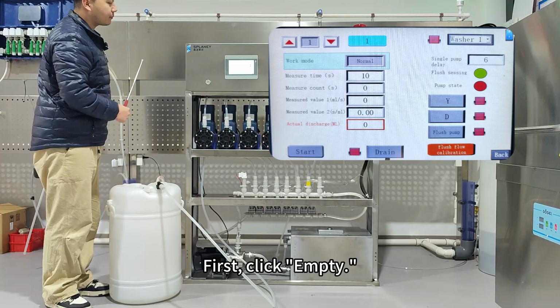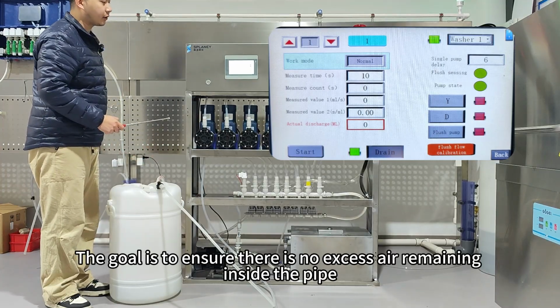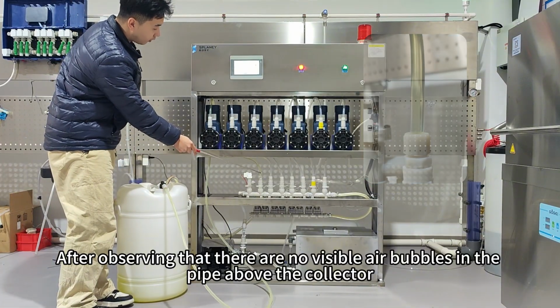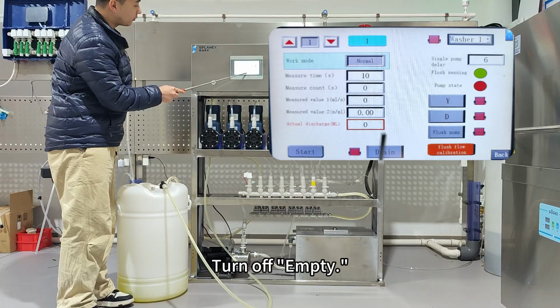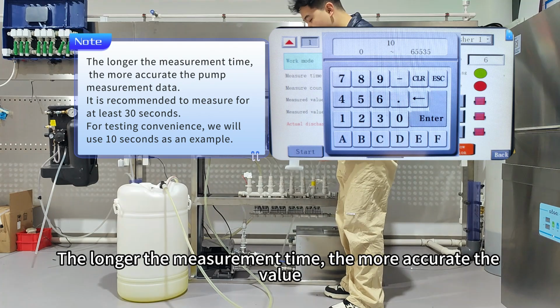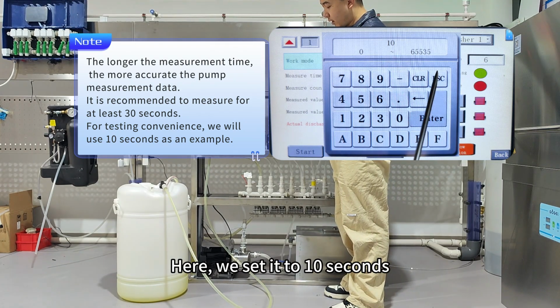First, click Empty. The goal is to ensure there is no excess air remaining inside the pipe. After observing that there are no visible air bubbles in the pipe above the collector, turn off Empty. Now, let's enter the measurement time. The longer the measurement time, the more accurate the value. Here, we set it to 10 seconds.